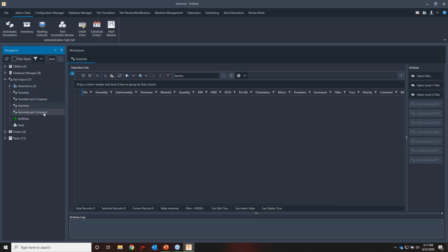With an automatic process, we go after geometry as well as any metadata within that file. This is what we're going to be using for Inventor native data because as we go after assemblies, we have access to information like the bill of materials, which has material quantities and some other properties about that particular assembly. We can bring all that information in at the same time and start to fill out some of the part requirements automatically before we get to the nesting process.